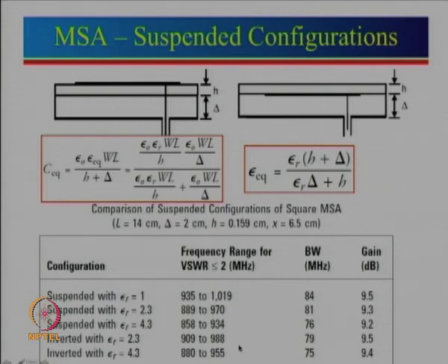Generally for commercial applications, one uses FR4 substrate. Commercial applications can be, let us say, designing a GPS antenna, or use for cellular communication, cell tower radiation and all that. But for defense and satellite communication, generally performance is much more important, and thermal variation and other factors are also important.